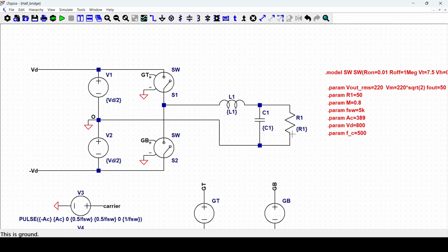So in a situation of light load, the LC tank is resonating a lot because not much current and energy can pass through the resistor. So we want to work at high loads, so a lot of current gets absorbed by the resistor. We want a low Q for an output filter, and a value we can assume is just 0.7 for Q.